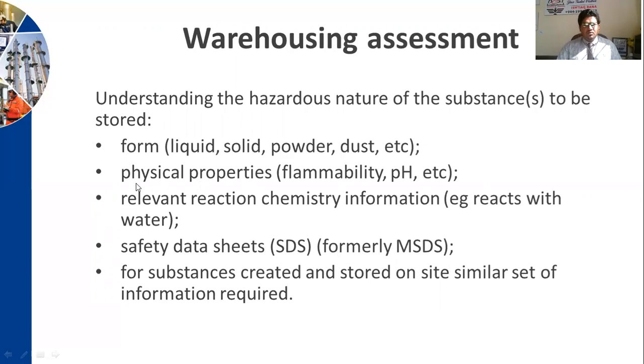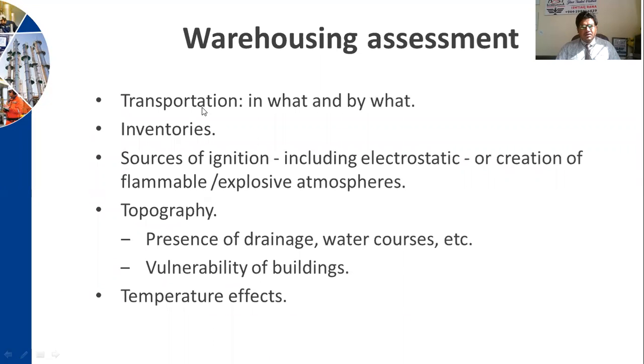Warehouse assessment, how are we going to do it? Understanding the hazardous nature of the substances: form, liquid, solid, powder, dust; physical properties, flammability, pH, etc. Relevant reactions and chemistry information, such as reacts with water. Have some SDS or formerly MSDS, like safety data sheet or material safety data sheet, or for substances created and stored on site, a similar set of information is required. Transportation and inventory, sources of ignition, including electrostatic, or creation of flammable explosive atmosphere.